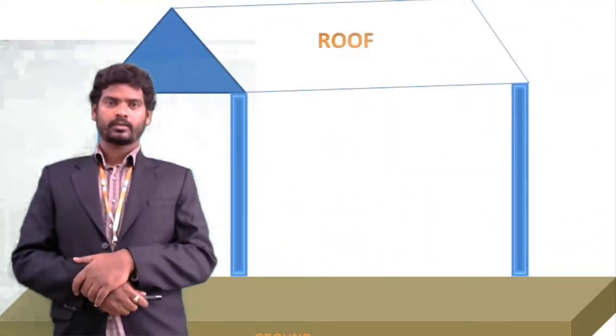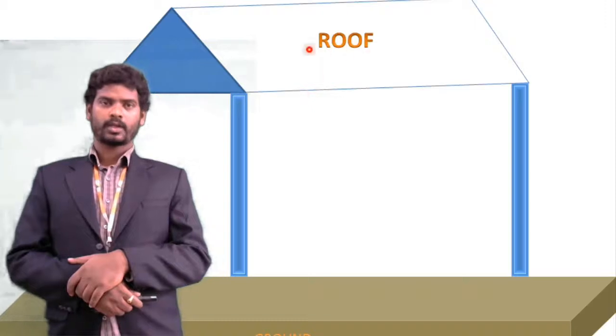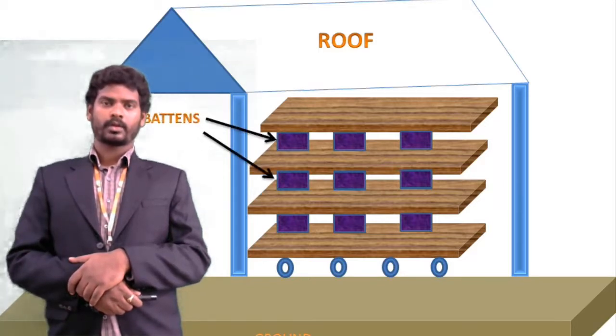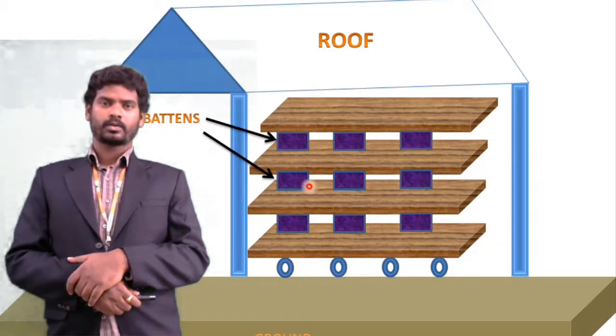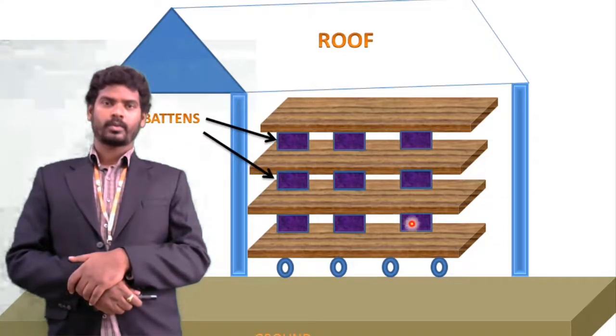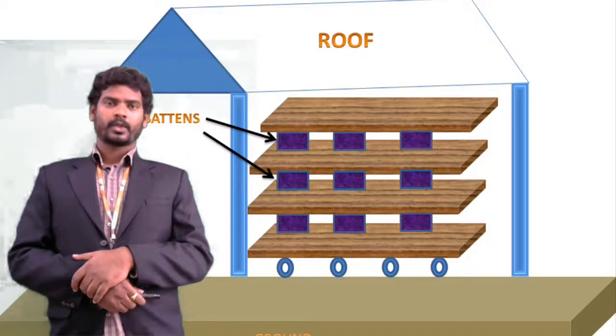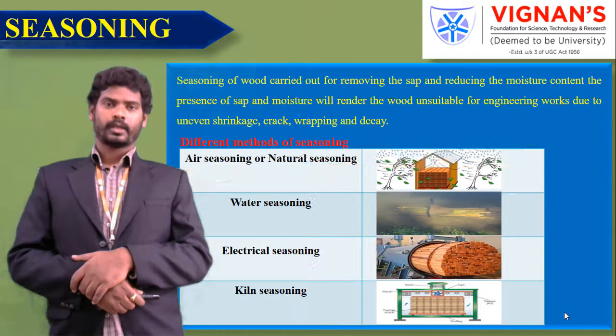In this method, the sawn timber is stacked in a dry place about 30 centimeters above floor level, with longitudinal and cross pieces arranged one upon another, leaving a space of a few centimeters for free circulation of air. It is fit for carpentry work after 2 years and for painting works after 4 years.